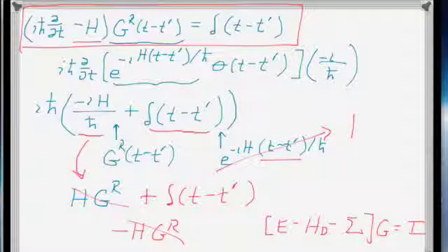For the chemical potentials on the last part you're going over, how do you know those? They're given by the chemical potentials of the contacts. So you know the doping of your contacts, and if you know the doping, then you know where the Fermi levels are. And if there is an applied bias, then they're going to be split by the applied bias.